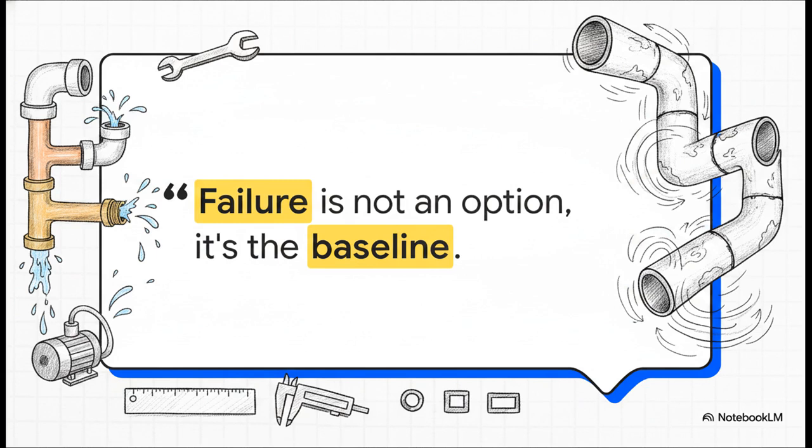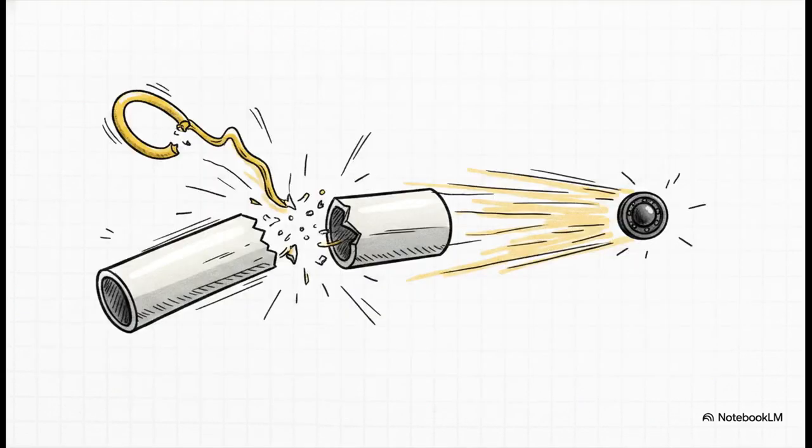Because let me tell you, when you take industrial fluid dynamics and try to apply them using off-the-shelf hardware store plumbing parts, you're definitely going to encounter some frustrating realities about manufacturing tolerances. Case in point, what I call the O-ring dilemma. If you try to build a custom check valve using a standard 3/4-inch PVC slip adapter, a rubber O-ring, and a steel ball bearing, you'll quickly find out that not all PVC is created equal.